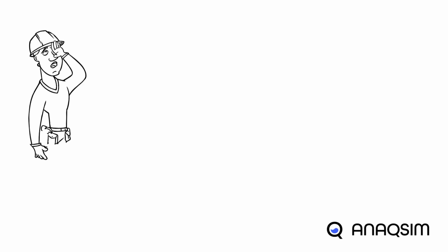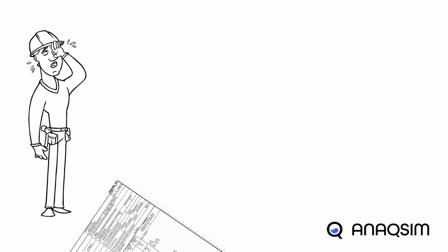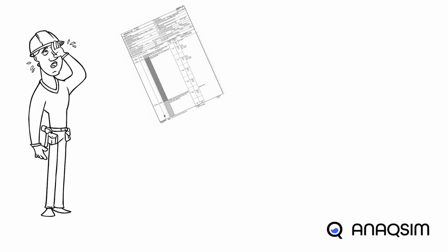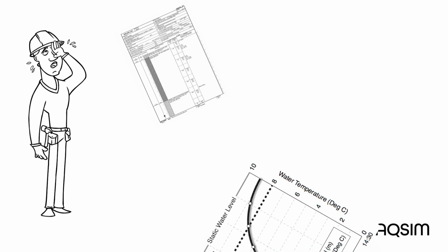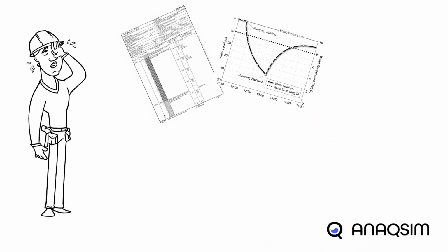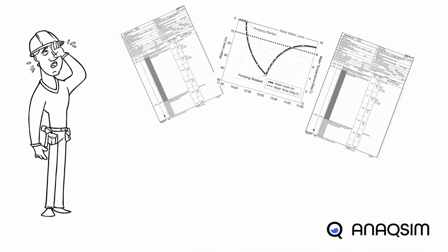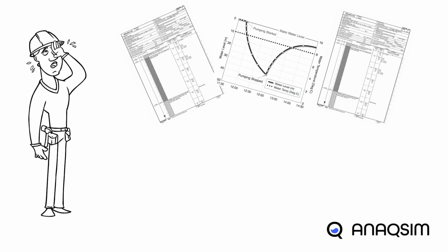If you've worked on site-scale projects, you know the pain points. Most of the time, you only have data on the saturated thickness of the aquifer at your site. The local groundwater flow direction is inferred from a few wells. Local geological conditions are shallow, pieced together in phases, with boundary conditions beyond the site often uncertain.